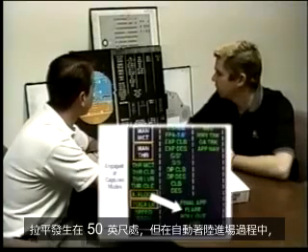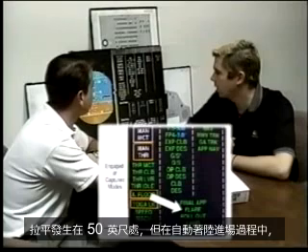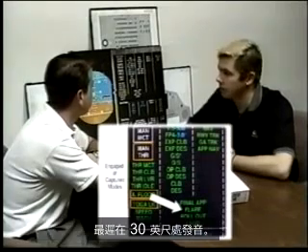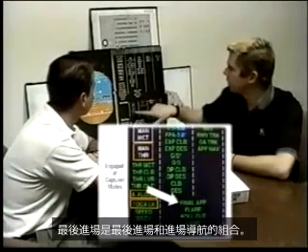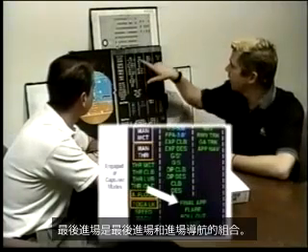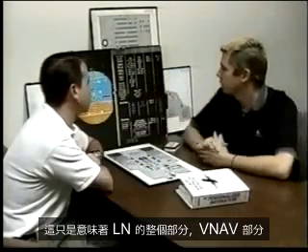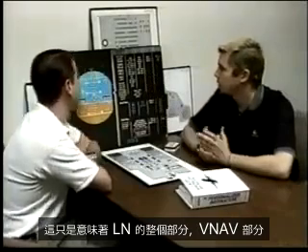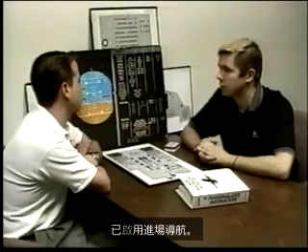Flare? Flare occurs at 50 feet, but during an autoland approach has to be enunciated no later than 30 feet. Final approach? Final approach is a combination of final and approach nav, and it just means that the entire LNAV VNAV portion of the approach nav approach is engaged.